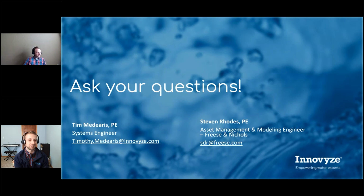Yeah, absolutely. That's awesome. Kind of similar to that, Evan asked, is there a break point? I mean, you had 20 CPU cores and were able to do that, but is there a break point where trying to be too accurate and represent hydraulic elements will degrade the model performance? Thinking about the number of weirs on the clarifiers, and things like that. So I guess he's actually looking at the actual hydraulic elements, not so much the time, maybe.